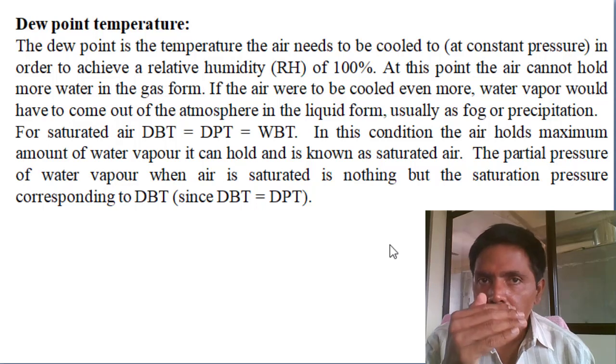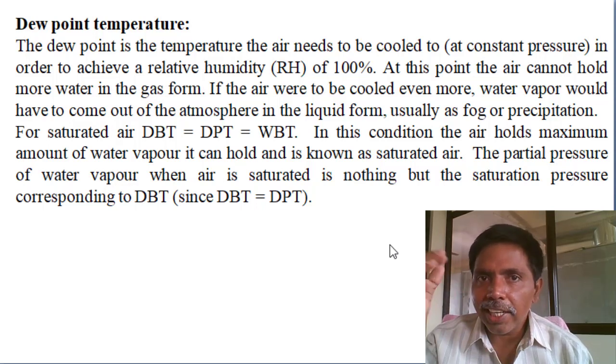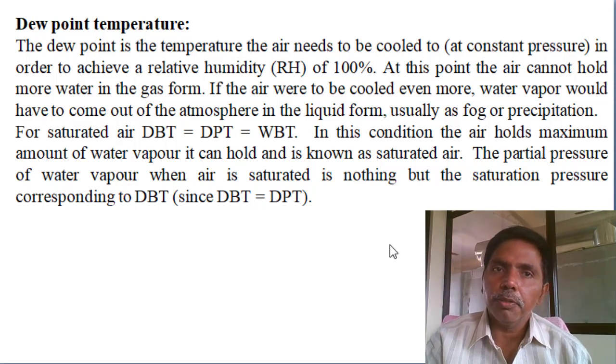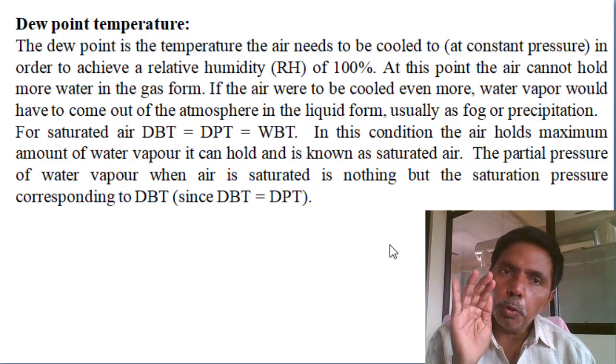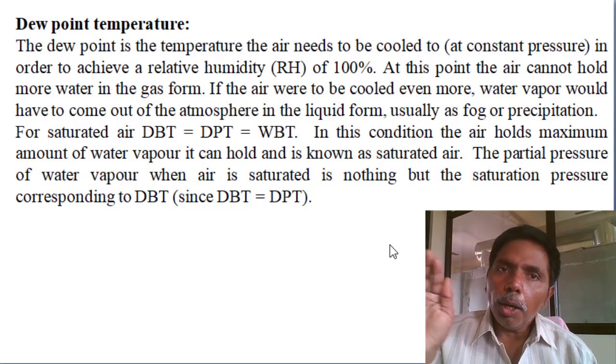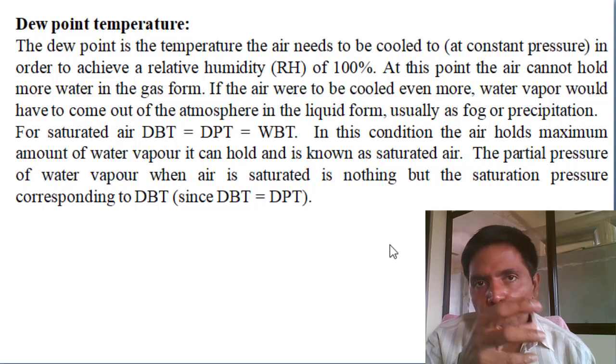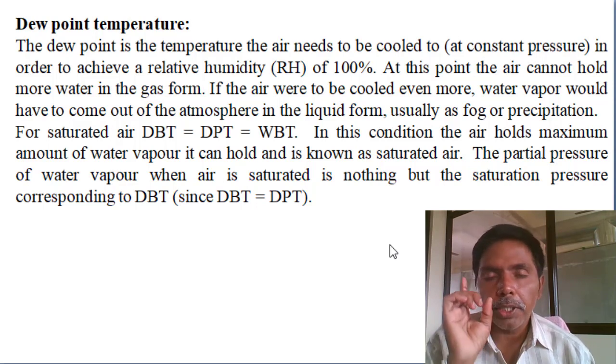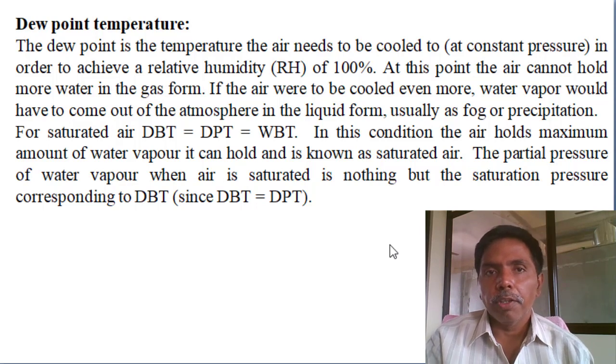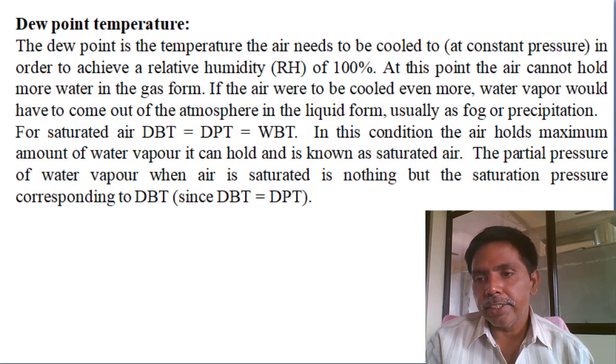Because only below that temperature will the condensation of the water take place. So we want to cool the air up to the dew point temperature. Only then can you remove the moisture. For that purpose, dew point temperature is very important for designing the air conditioning system.